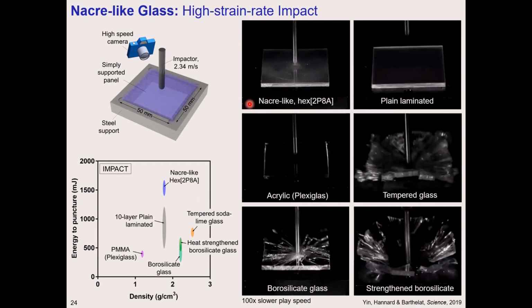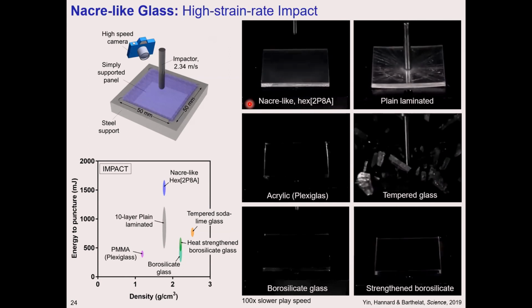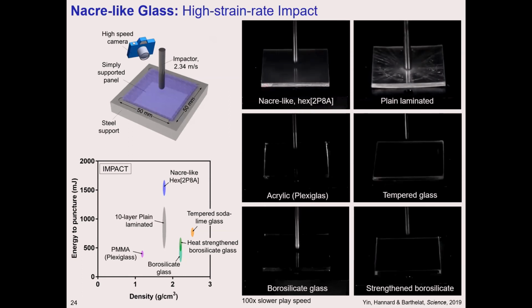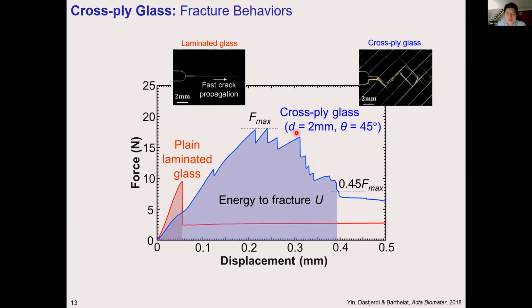Dr. Nagamani has a question. Thank you for a very nice presentation. I had a question about how you measure work of fracture. Is it the area under the load displacement curve, or is there anything else? The work of fracture is the area under the curve. But in the fracture test, because the EVA, the interface material we are using, is highly deformable, you can almost never fully fracture the whole sample. The load will keep going forever.